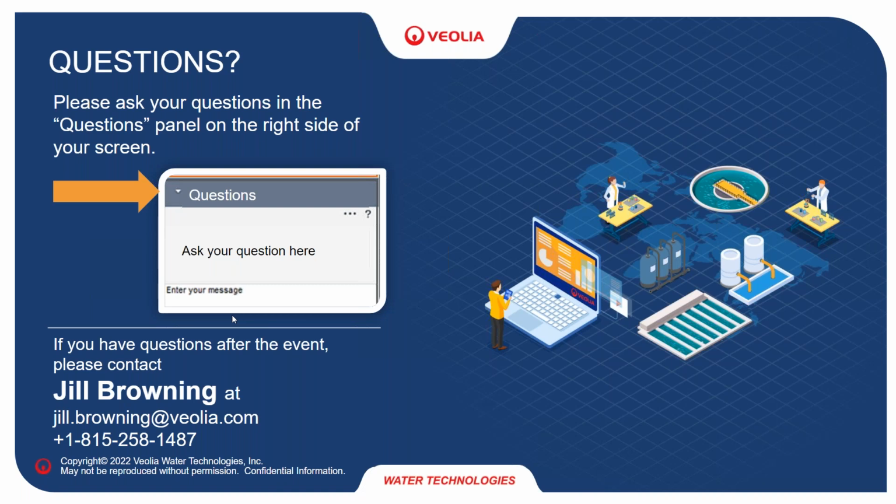Yeah, sure. So to be able to size the vessel, we would need to know, obviously, the total suspended solids that are coming in to our vessel, along with the composition of the liquid, pH and temperature. And with that, we can either do an assessment of something that we have done in the past and provide some preliminary sizing.